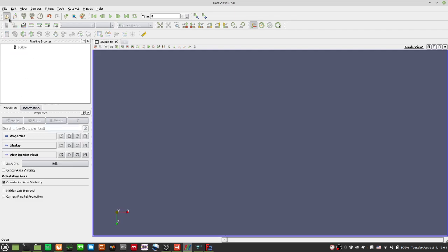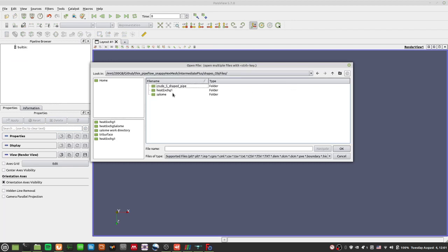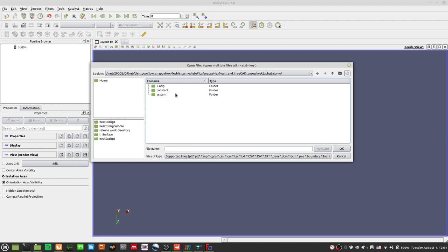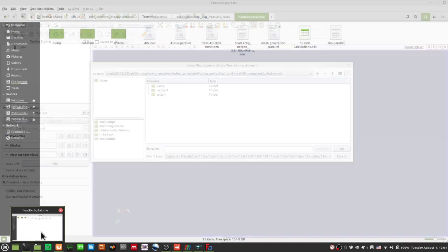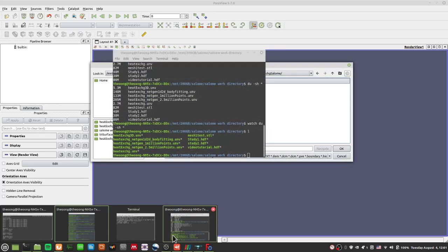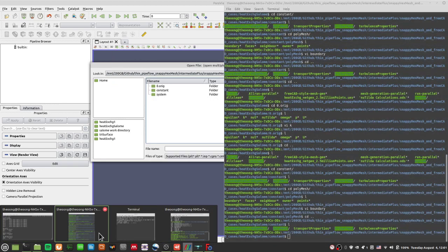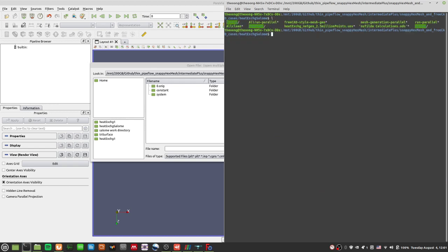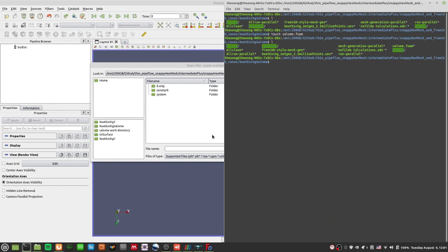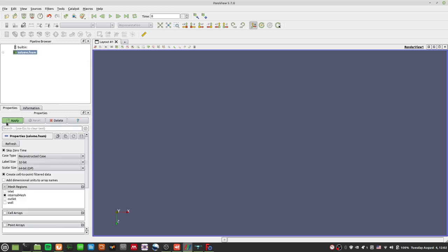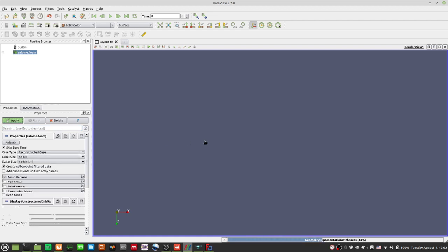And when I open it, I'm going to reopen it. I'm opening this in ParaView. Before doing that, I need to touch a Salome.foam first. So I go through the summary first, touch Salome.foam, and you see this ideasUnvToFoam is done. It will just make the mesh for us, so no need to do blockMesh or anything like that, which is great. You can do the Salome.foam and it will load up everything for us.